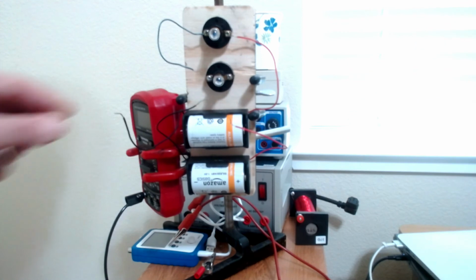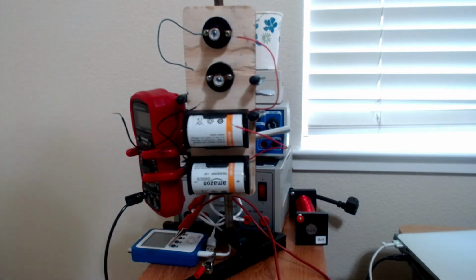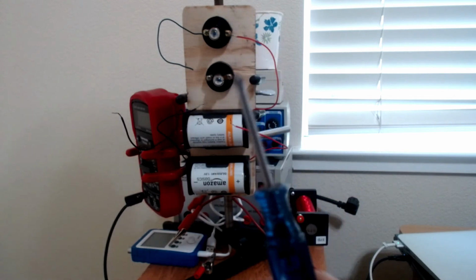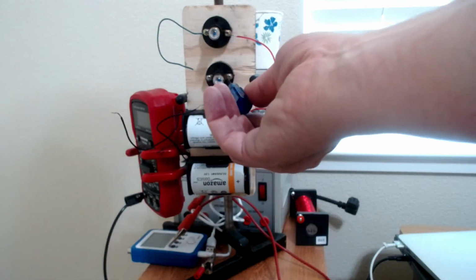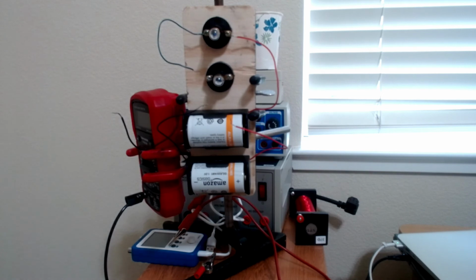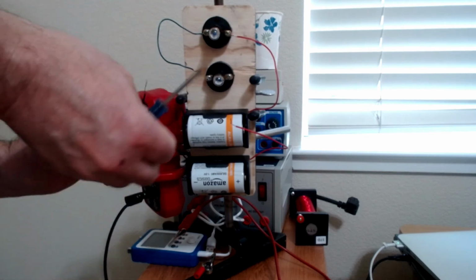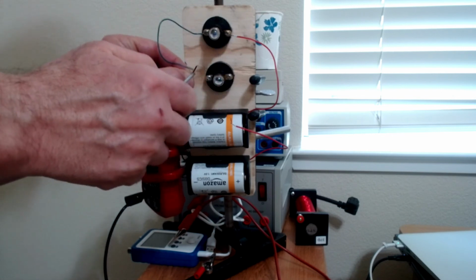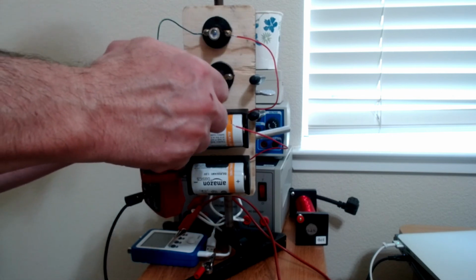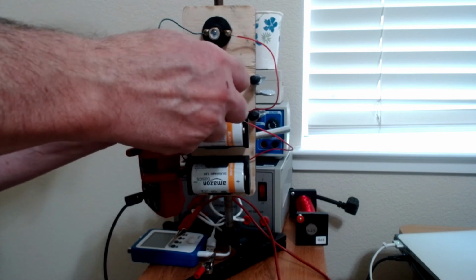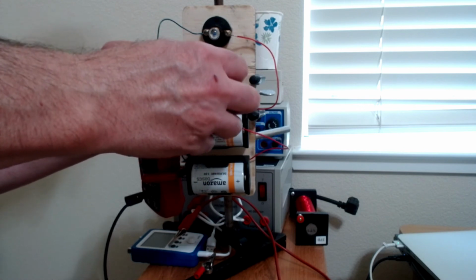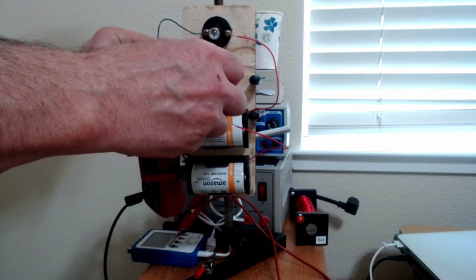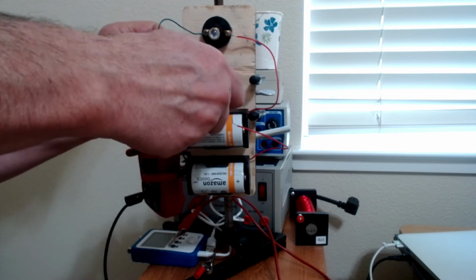One of the issues you have to deal with here is that you're going to need a screwdriver. Your lab kit comes with the screwdriver, and you're going to have to screw the wires on here. Now, these are very small, so it's hard for me to see, and I'm going to have a hard time screwing this in. If you're going to turn the screwdriver clockwise, then you want to wrap the wire clockwise. Otherwise, it won't stay in place.